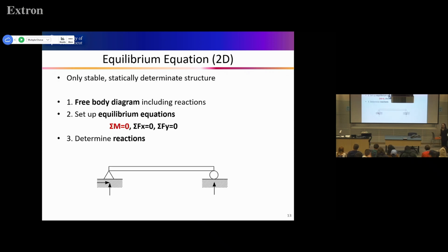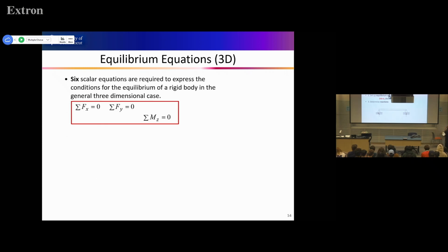Okay, now moving on to the third learning objective, the equilibrium equations. We talked about how to solve the problem: draw the free body diagram, then solve the Fx and Fy equations, so find the resultant. If in the x direction and y direction they are 0, then that's equilibrium, right? Now we are adding one more equation, the moment equilibrium equation. When we solve these 3 equations in 2D, we can find 3 reactions. So this is the step to solve.